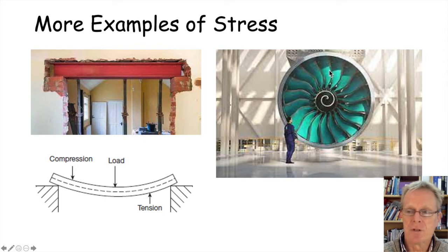And there's also a huge bending load from the colossal amount of air that is pushed through the engine, particularly on takeoff. So these blades are subjected to enormous stresses, and it probably takes several thousand man-years of engineers' time to design them, to get them to work properly and also to be light as well. But they're still looking all the time at stress and strain.